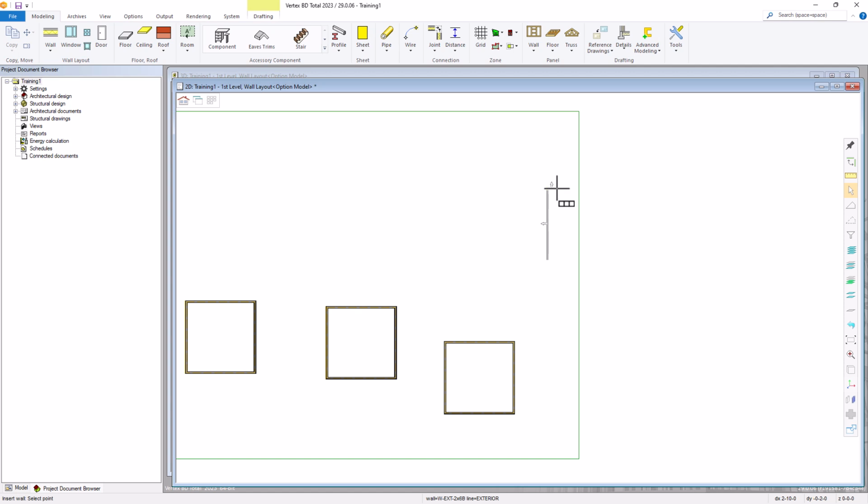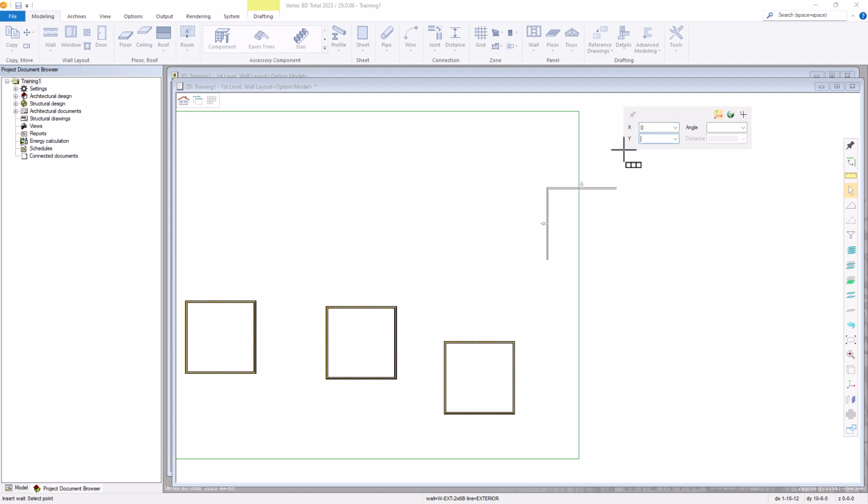Let's go over to the right, hitting the U key and locking the horizontal constraint. And again, 20 feet. Now let's go up 10'6", but this time let's use the XY coordinate system. So we're going to make sure that we do not see our constraint. So we're going to move it over to remove the constraint symbol. Since we want to go horizontal, we're not going to move in the X direction. So we'll hit 0. And we want to go up 10'6" in the Y. Hit return.